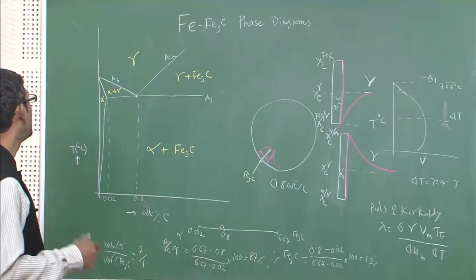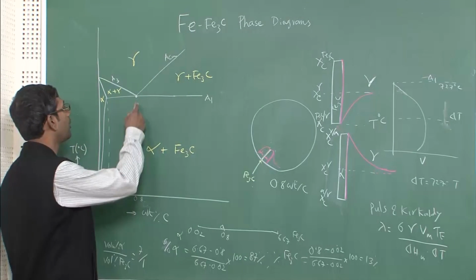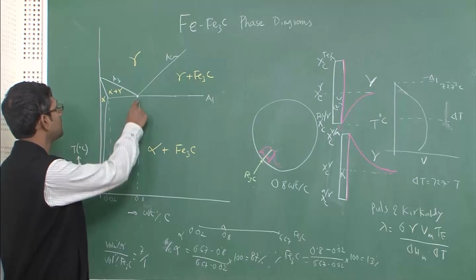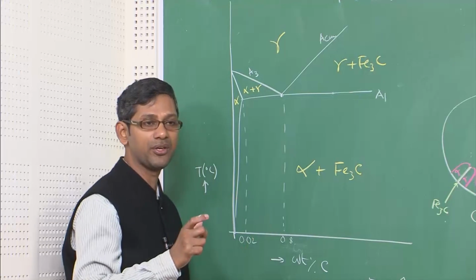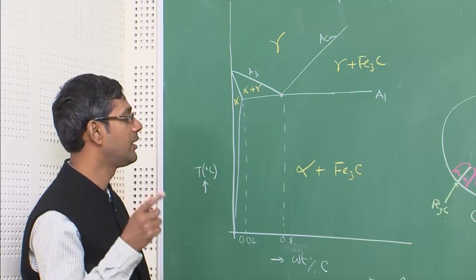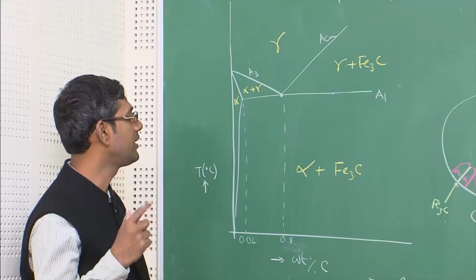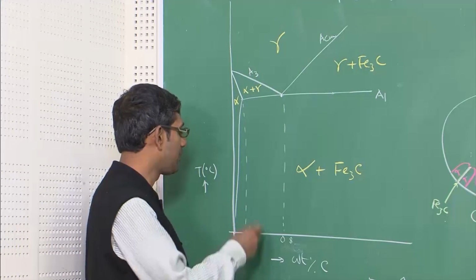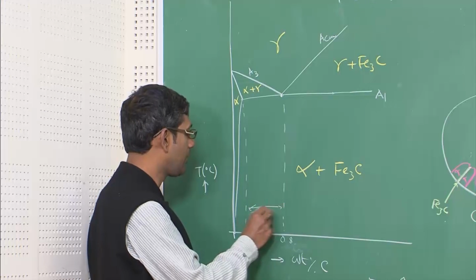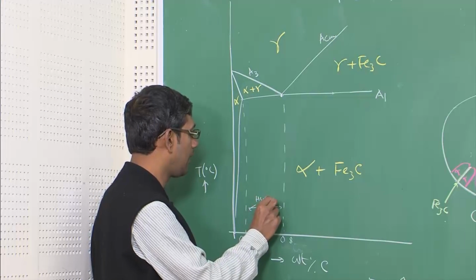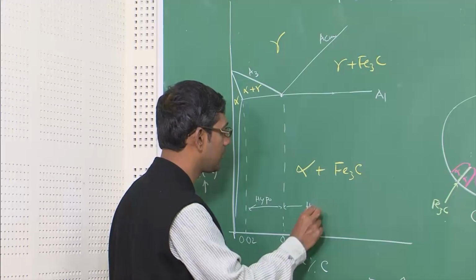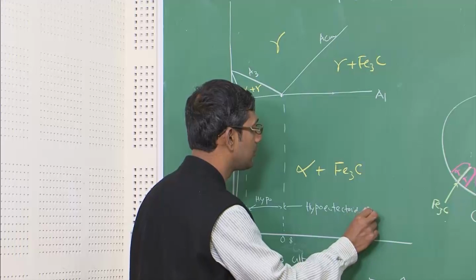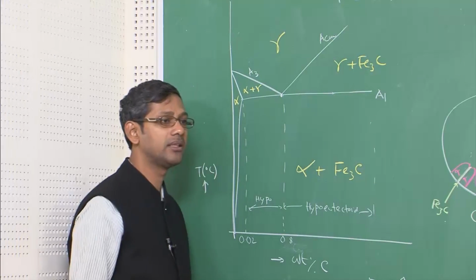As you know, I am only discussing pearlite for the alloy with a concentration of 0.8% carbon. For this alloy, pearlite will be the only microstructure. I showed you an image of large pearlitic colonies. But I also need to discuss the hypoeutectoid and hypereutectoid alloys. What will happen, I am going to discuss in the next class.